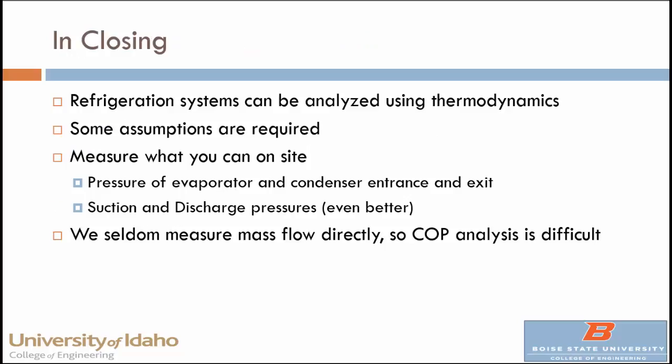So that's it. We can use the thermodynamics from our undergraduate thermal class to analyze these things. We have to make some assumptions or some measurements. So if we're on site, if we're actually looking at it, it'd be great to know the pressures of the evaporator. And usually the best thing to do is just look at the suction and discharge pressures of a compressor. Big refrigerant systems usually have gauges there. That's the best data.